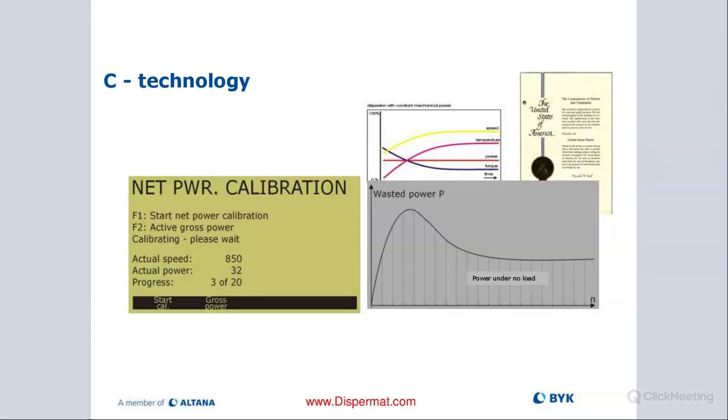We have the ability on the AE to do what's called a net power calibration. Basically, before you are running any material, you can set the machine to an absolute zero value point. That means we are not including any energy that the machine uses to operate itself. Obviously, without product, the dissolver, when it's spinning, already needs energy to move the blade.